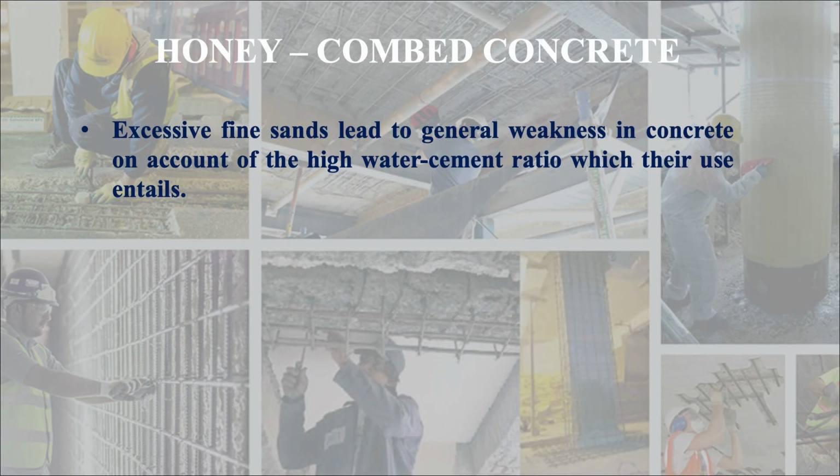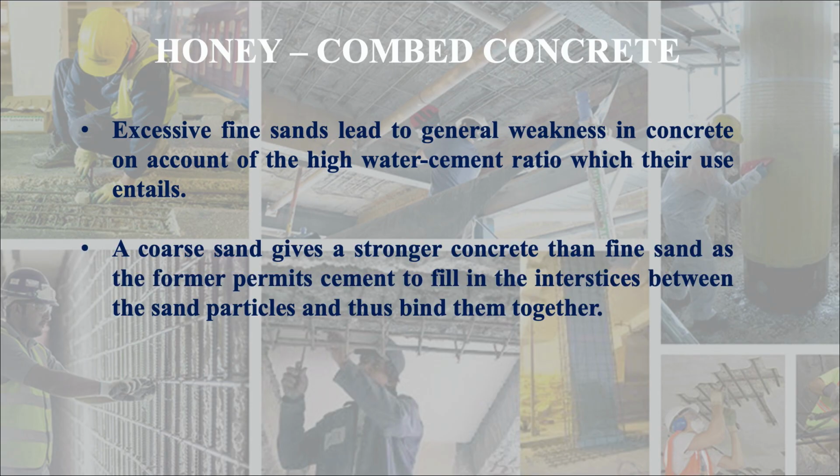Excessive fine sands lead to general weakness in concrete on account of the high water cement ratio which their use entails. A coarse sand gives a stronger concrete than fine sand, as the former permits cement to fill in the interstices between the sand particles and thus bind them together.